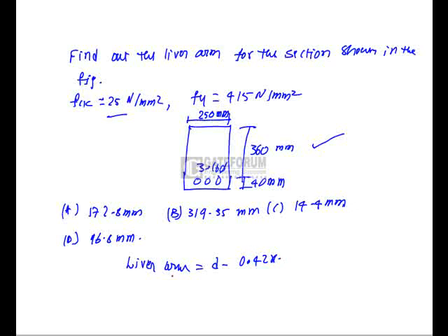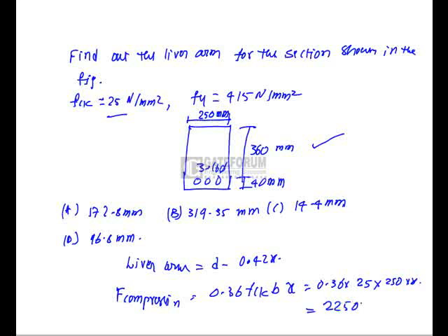Force in compression. We know that 0.36 fck b x, that is 0.36 into 25, b is 250, into x, that is 2250x newtons.